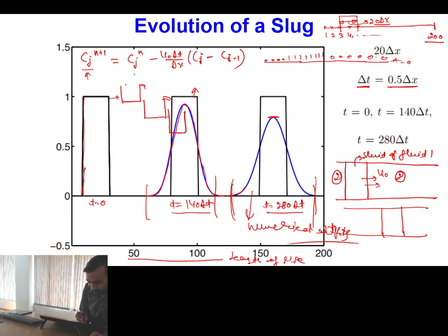If I say this container was fully filled at initial time and this container was partly filled, when solution is advecting because of the velocity, first what should happen? If some more water is pumped into this, then whatever the spilled over water is there, that should first fill the next container, and after that it should spill to the next cell. Is this point clear?